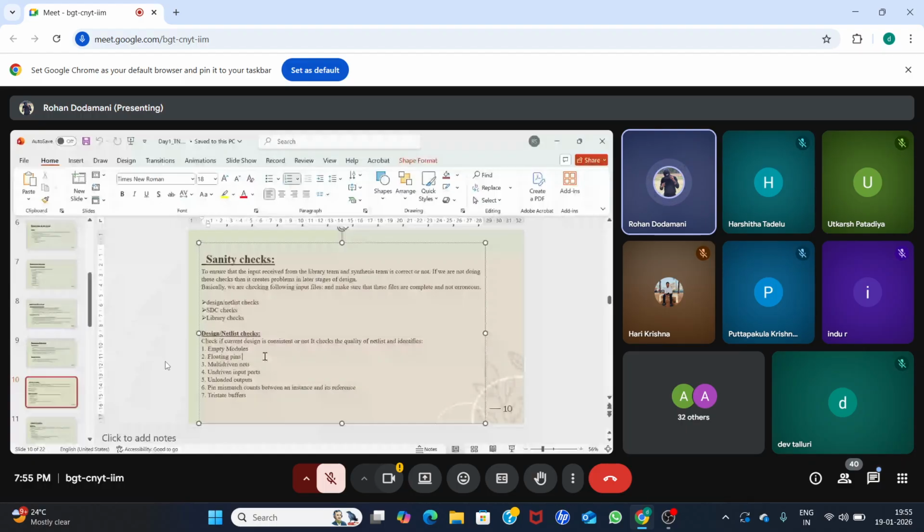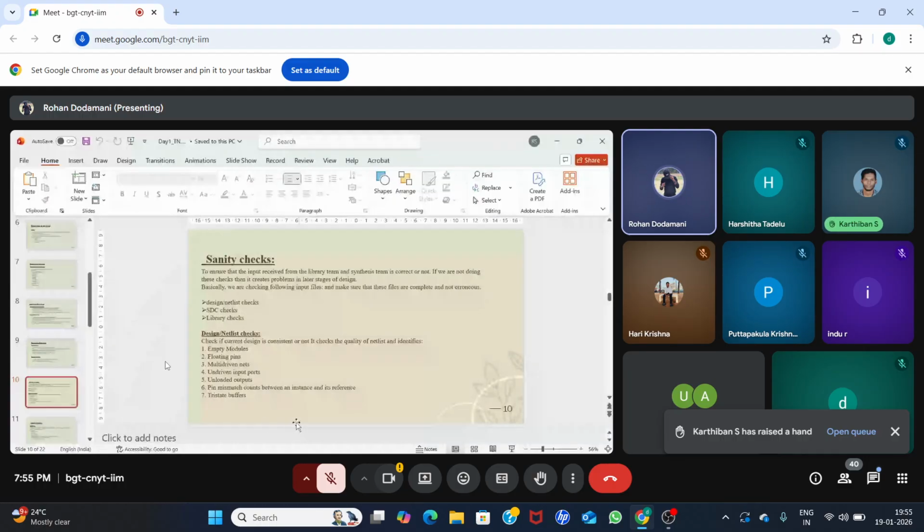And any multi-driven nets. A single net driven by two different nets, that we call multi-driven nets. If anything like that is there, again it will affect the timings. So that should be checked at netlist check time, when checking timing.